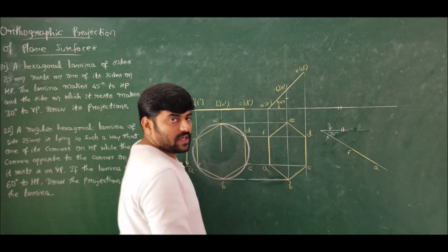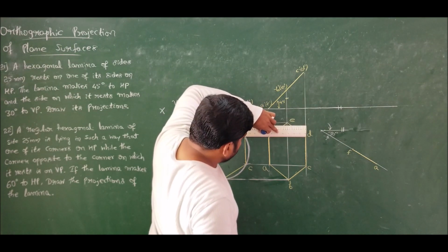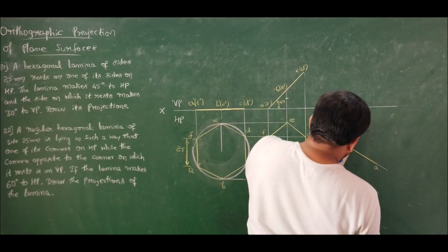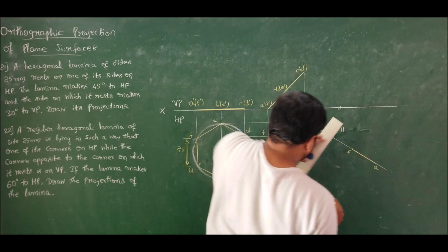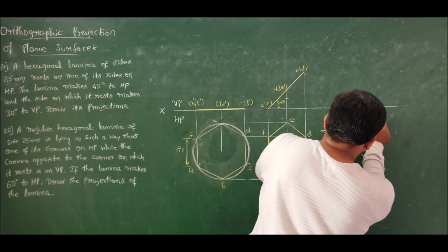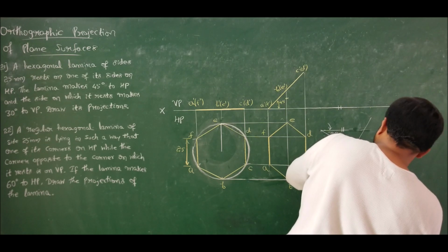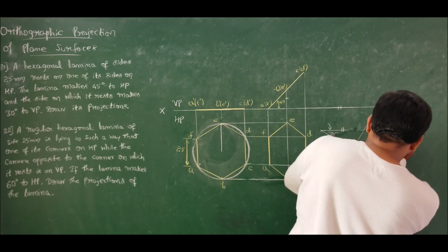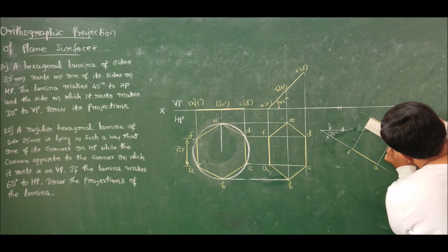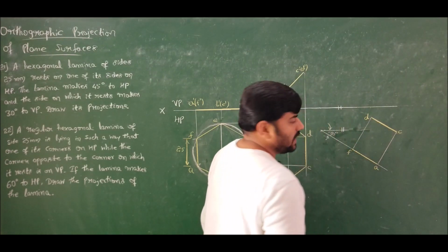Now DC is parallel to FA, and FD and AC are perpendicular to FA. So first you transfer FD and AC, which are perpendicular. Transferring the perpendiculars, that is FD and AC, transferred. So what I got is corners C and D.